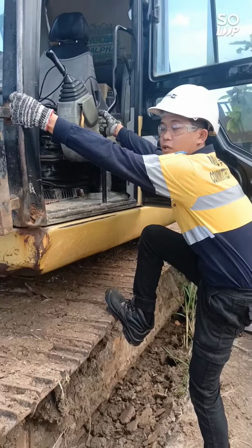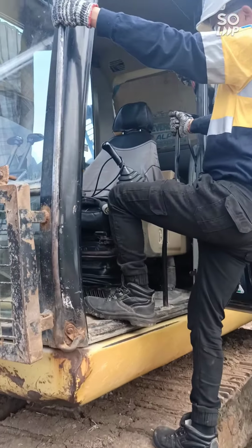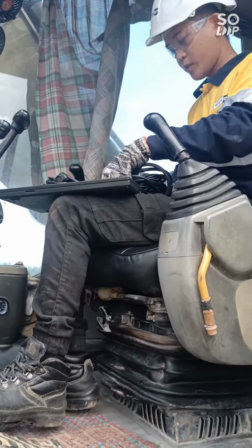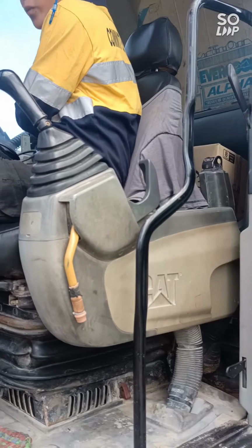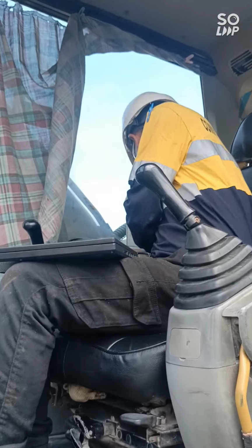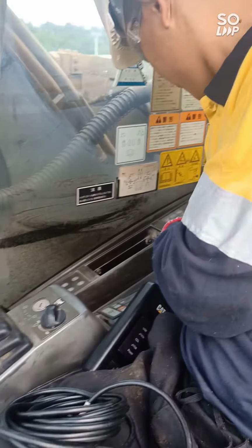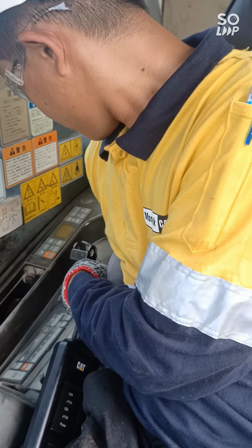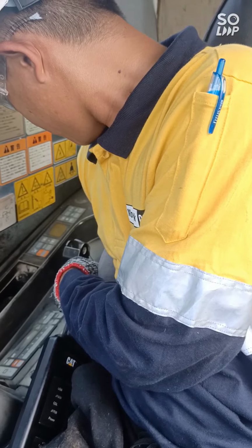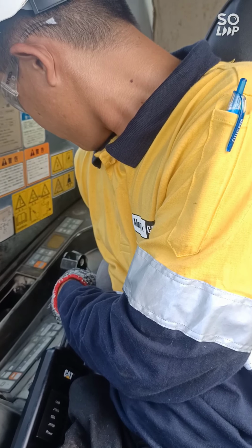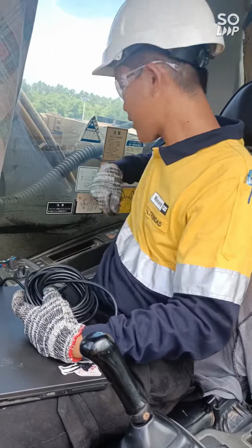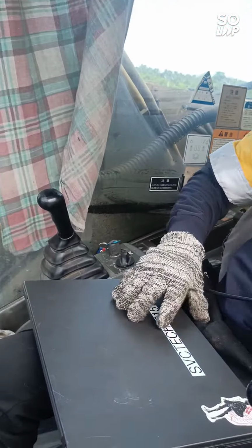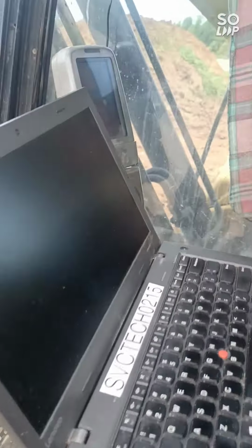We should ensure 3-point contact when lifting up on a machine. Then we install the Caterpillar Electronic Technician. After installing the Caterpillar Electronic Technician, we should turn on the machine, turn on our laptops,